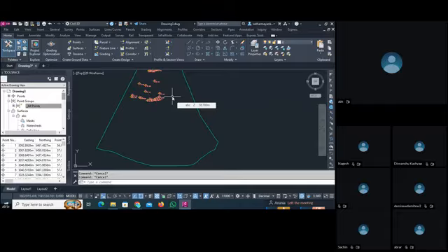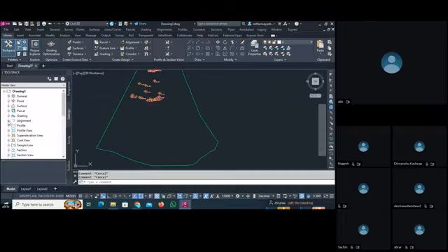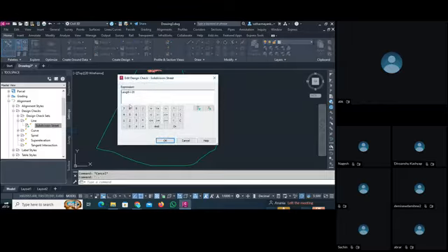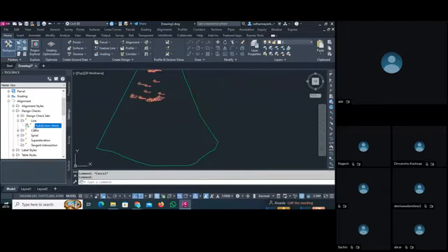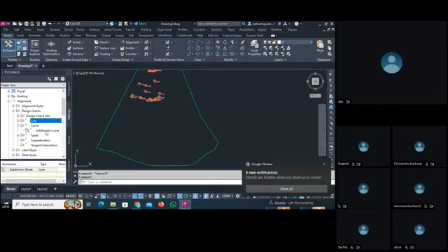All those things before starting the project. So you can control your design check set from here also, in alignment in a design check set. If you have a line code, you can edit this code from here. If you want to add the length, or add anything to the line, you can add it from here, provide your own value, save that code and use that code also. This is one method. You can do this for the line, for the curves, for the spiral. So this is one path.